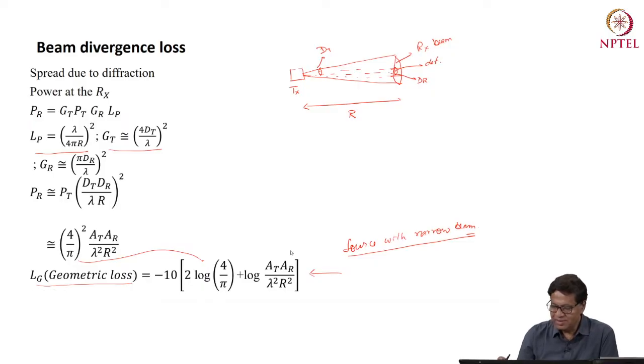So just to give an idea, for example, if I have theta divergence as 2 to, for example, 10 milliradian, this is theta divergence. It will give me a beam spread on the receiver, which is 2 meter to 10 meters. This is beam spread. So the beam spread is quite high. So I may not be requiring any tracking mechanism. So no tracking may be required.